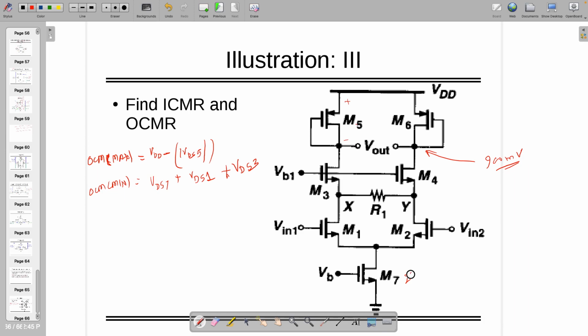Even if you keep 250 millivolt each, if it goes from here to there, then it's gone. You have some margin, right? Then it will work. So if VDD is 1 volt and each one of the transistors has 250 millivolt, it's very tight. It does not give you a guarantee: in the slow corner, one of the transistors will go to, let's say, 200 millivolt and the other is gone, right? That will happen.